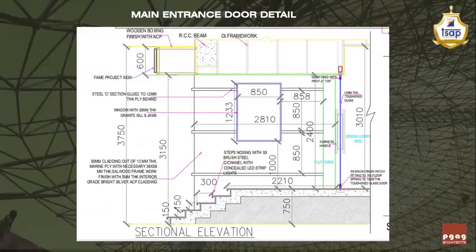You need the flexibility for the planning of wooden paneling and the gypsum paneling around that, and sometimes the span also does not allow you to construct the RCC lintel. Because of that, many a times we need to construct an MS lintel for the main entrance door paneling.